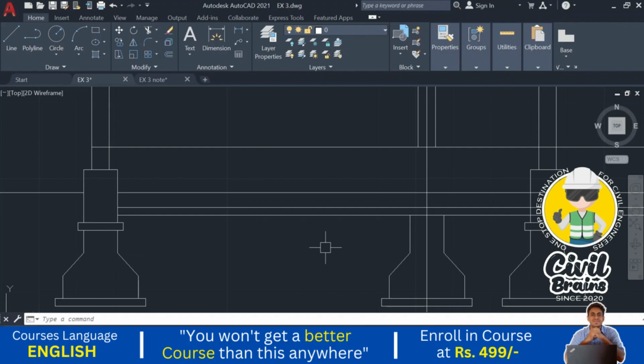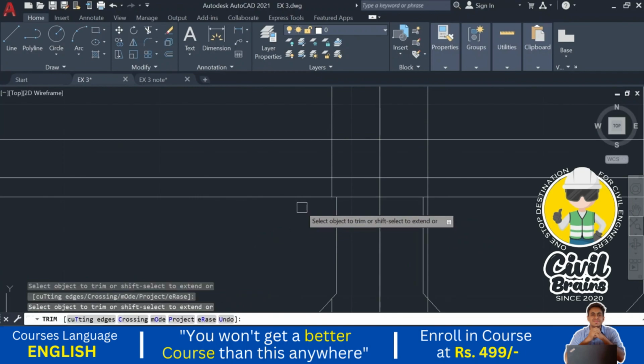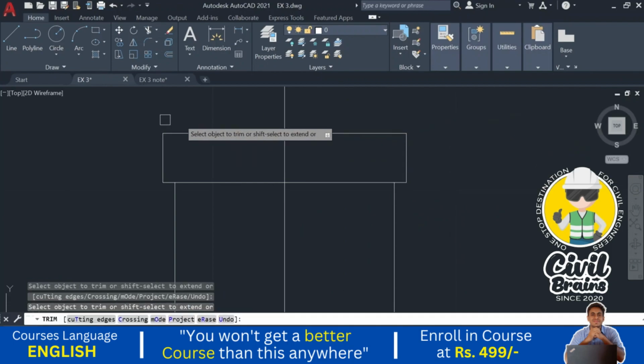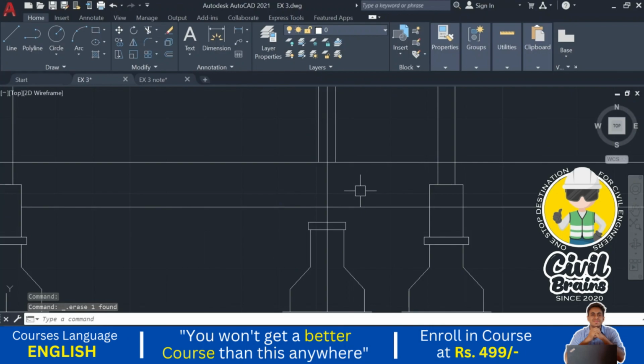I just go offset width of the trench first, we need 0.25, and just trim this one. So width of the trench we have provided. Next above that one, width of the foundation we have considered 0.3, and offset 0.15.